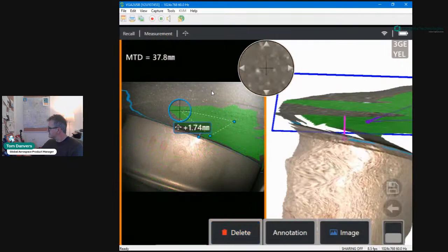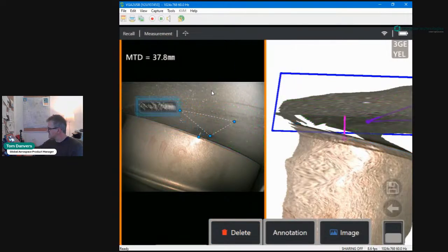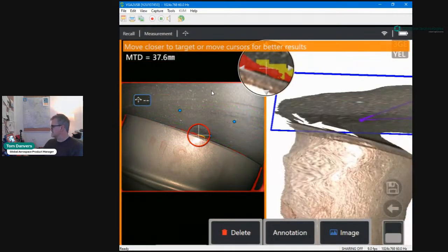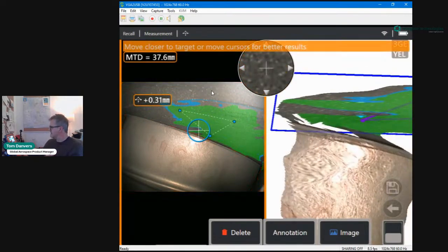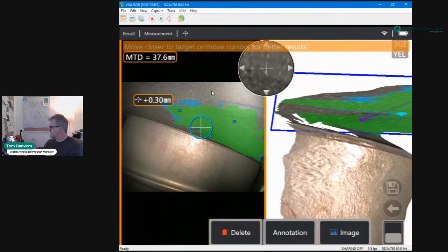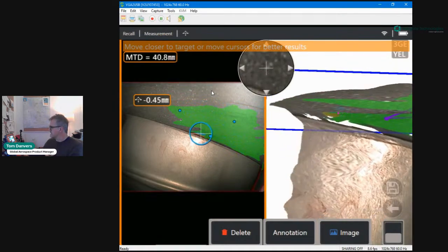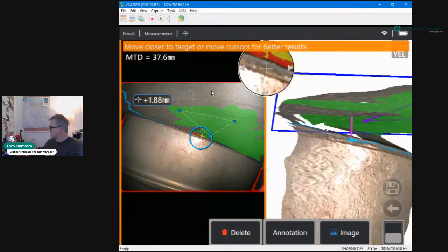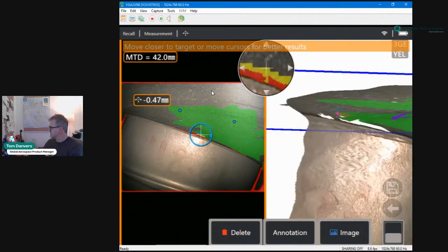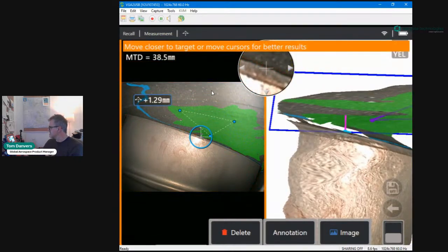my measurement plane and repeated what I just did, let's move that across over there. There's, in this case, a very small amount of material or a surface that doesn't have any 3-dimensional information, hence the red flood. And then as I move the point closer to the reference plane, my 4th point is actually already on the abradable liner. So the depth value is actually negligible until it snaps onto the edge of the blade, where you see it jump from essentially less than 0.5 millimeter to 1.5 millimeters, 1.3 millimeters.